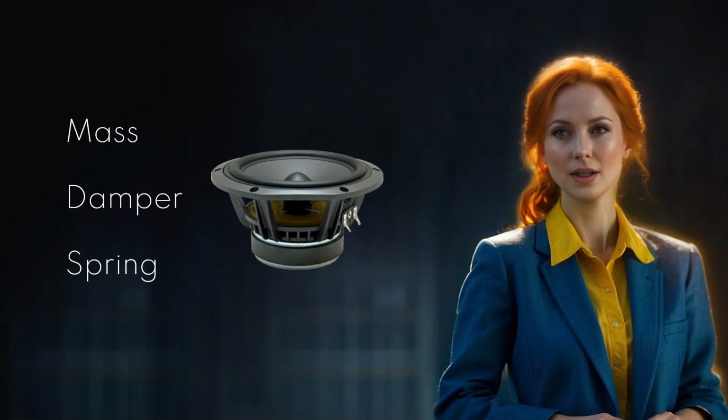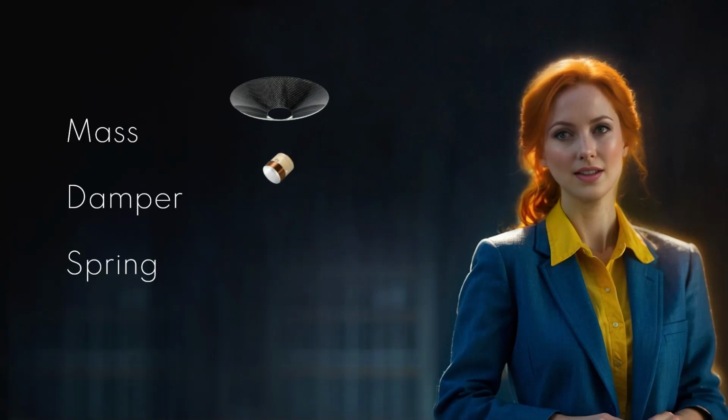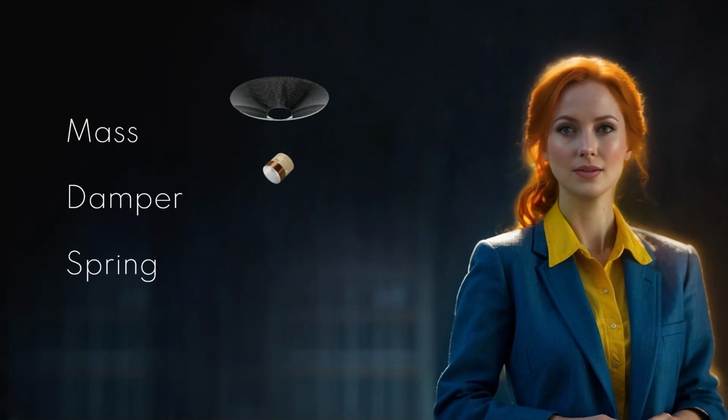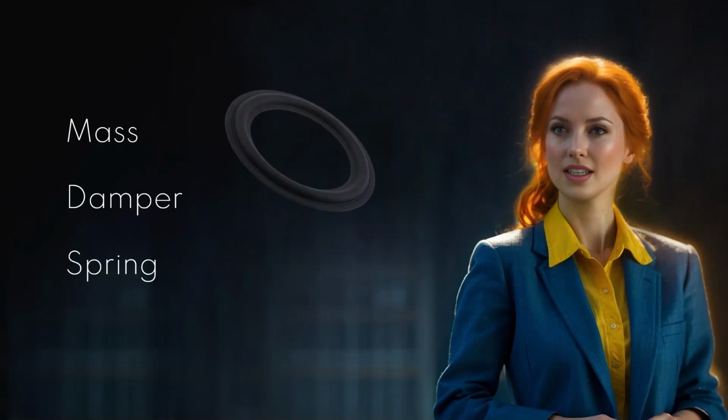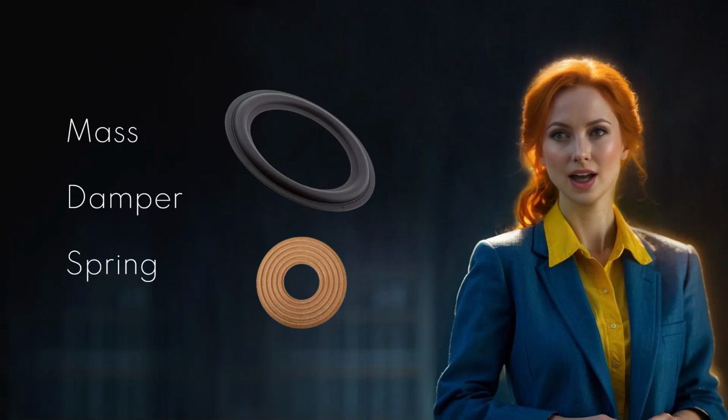The mass component encompasses various elements such as the diaphragm of the cone, the mass of the voice coil, the effective mass of other moving parts of the speaker unit, and even the added mass of the air that moves along with the cone. The damping effect in a speaker unit comes from the suspension system, which consists of the surround and the spider. It is important to note that the surround and the spider also double as the spring, working together to align the movement of the cone during the oscillation.